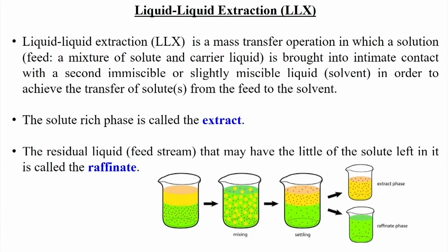It is a mass transfer operation in which a solution containing the feed, that is a mixture of solute and carrier solvent, is brought into intimate contact with a second immiscible or slightly miscible liquid in order to achieve the transfer of the solute or solutes from the feed to the extracting solvent. The solute rich phase is called extract, and the residual liquid that may have a little of the solute left in it is called raffinate.